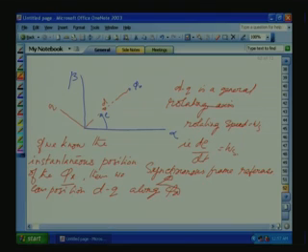So, what is the advantage? If our original IS is here, then IS can be split along psi r and perpendicular to it. That means there is a current component along this one, this is our original I_mr, and perpendicular to that one will be our I_r.